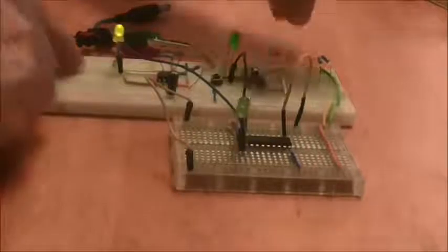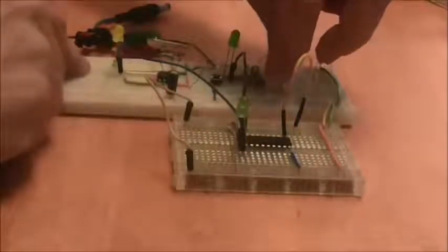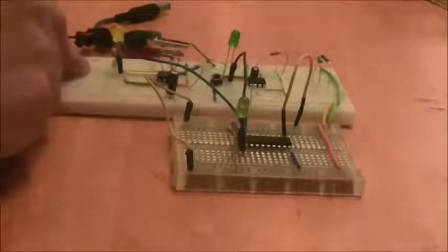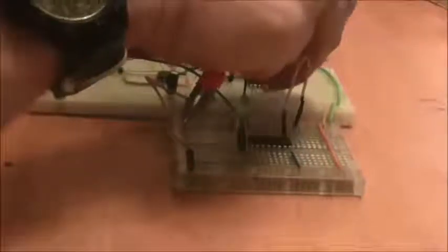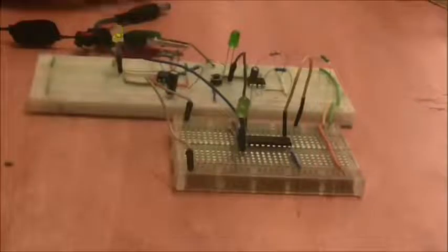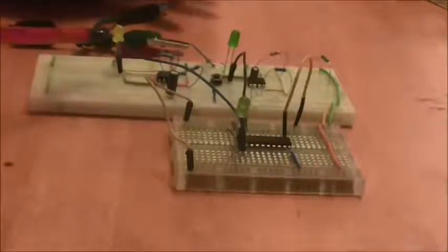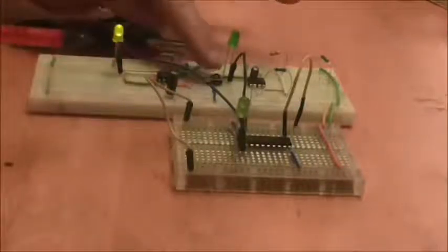And what I'm going to do now is I'm going to take this 47K resistor out, and I'm going to put a slightly bigger one in, and this is 220K, so let's put him in there. Excuse me a moment, there we are. We should get a slightly bigger time from the monostable, and what I want to watch is the clock pulse as well as the monostable.